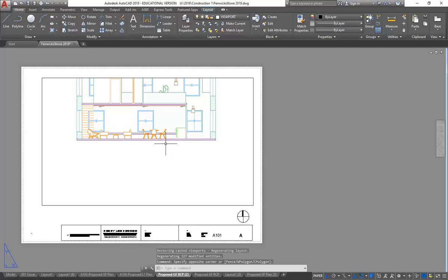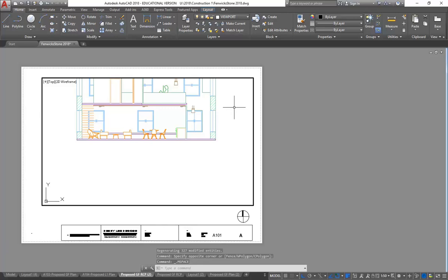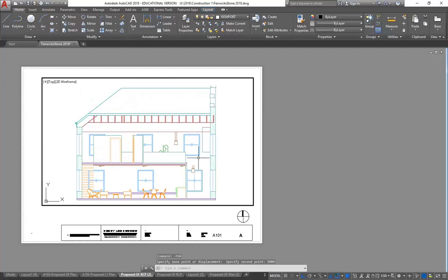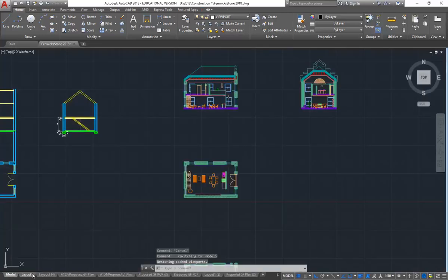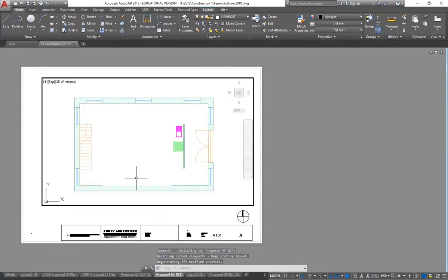So it's when you see that happening that it becomes clear why this option is so useful. So again, in that viewport, it's dash, P-A-N, dash pan, enter, and then you can click a point, move the cursor in the direction you want it to pan, and then type in that measurement, which I know is 5,000 because I've just used it. And then it goes back into exactly the same place. So it's just that extra little command that a lot of people don't even know is in AutoCAD, but it's been there from day one. And yeah, really useful when you're working on pages like this.